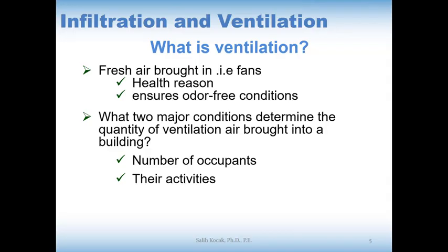And what two major conditions determine the quantity of ventilation air brought into a building? As we said, the number of occupants is important, and the activities that they are performing. Okay, so we said that a minimum of 15 CFM per person is required. So if we have one person inside, it is just 15 CFM minimum.